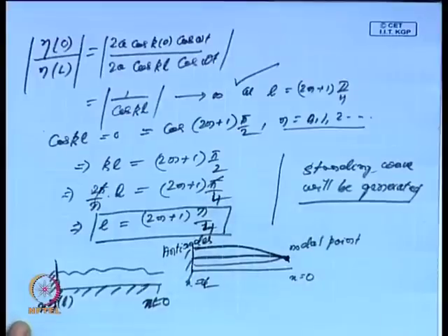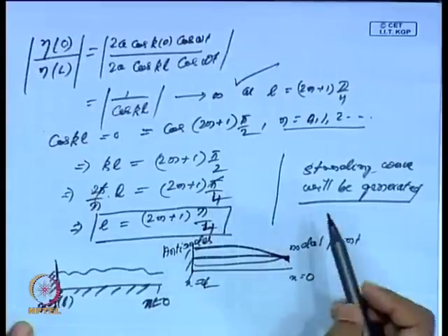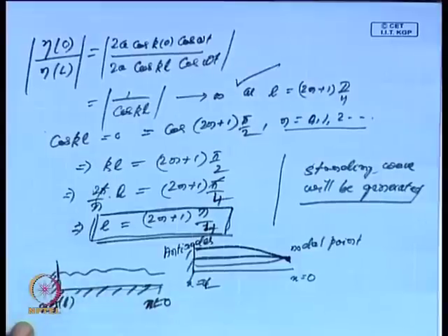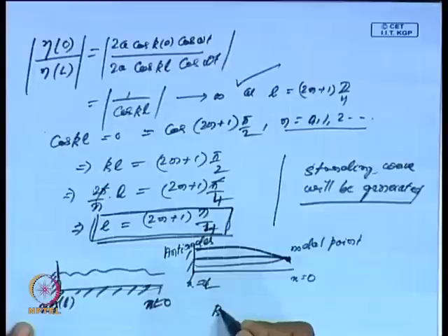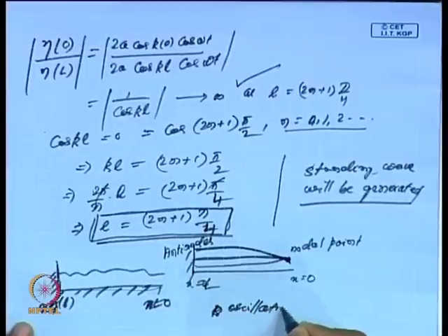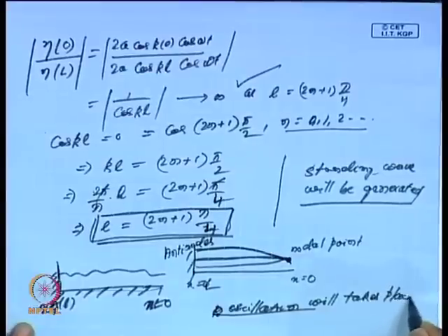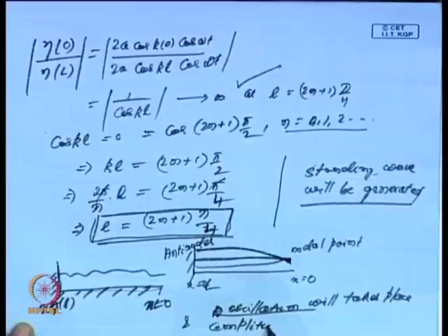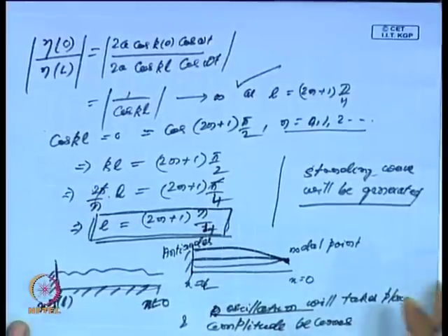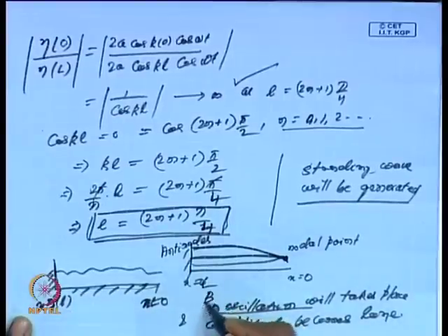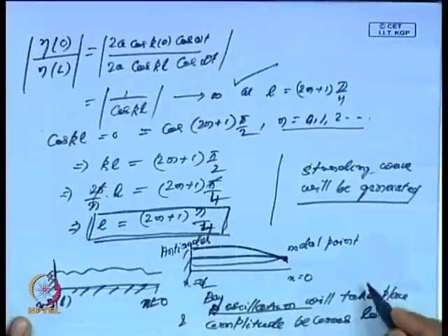So, that means when a wave propagates, it is a case of a one dimensional bay. When a wave propagates from the deep sea to the bay area, there is a chance that when L is equal to (2n+1) into lambda by 4, if the bay is a vertical one and this distance is L, then there will be a condition of water particle resonance. It will resonate, bay oscillation will take place, and amplitude becomes extremely large. In that situation, we always say bay oscillation has taken place. And amplitude becomes large. So, this is one of the very important points.